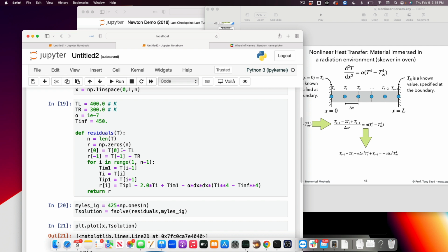With large values of alpha, we saw this flat curve, right? Because the heat was instantly transmitted to the rod and dominated it, right? But with smaller values of alpha, there's more resistance for that heat to be absorbed and communicated along the rod. Okay? Rounding error. When I change it to a very small number, then the system might not be valid in that case. So that's a very extreme situation. Because in that case, the heat transfer coefficients will become dependent on the temperature. There's another nonlinearity that comes in. So it's not a good representation.